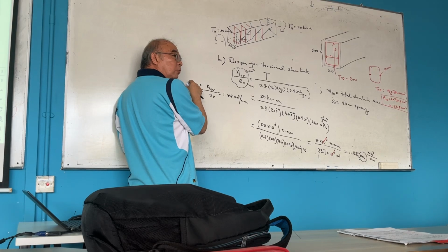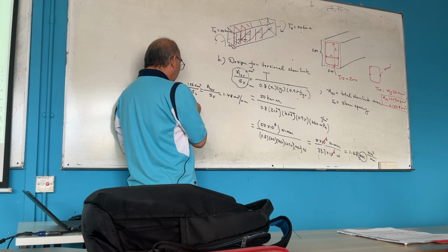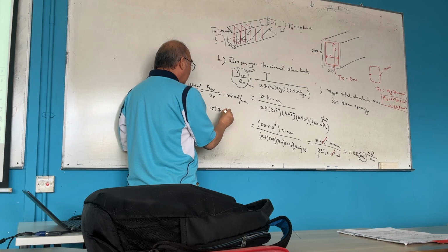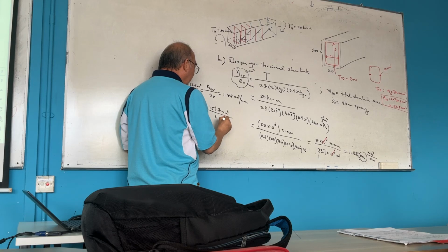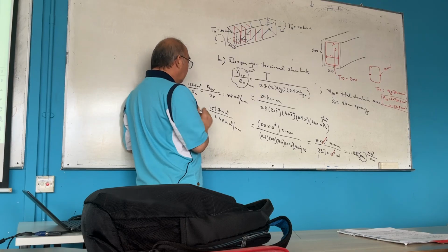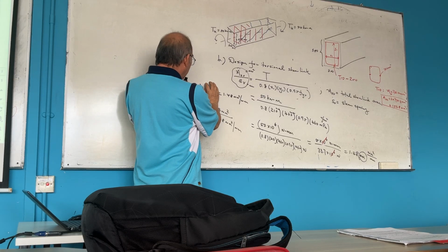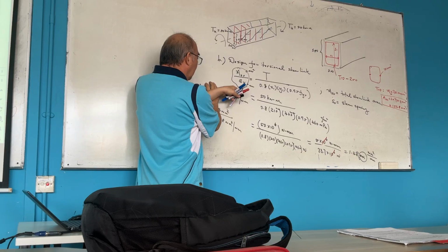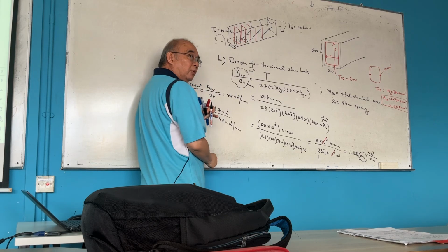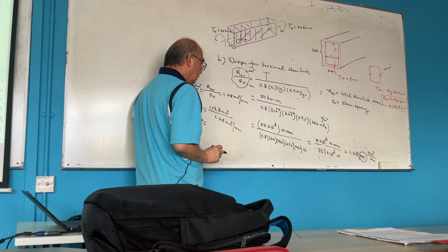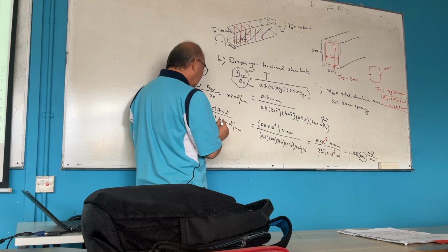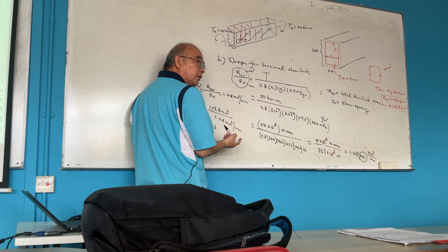Using ASV is 156.8. What is my SV? My SV would be equal to 156.8 millimeters squared divided by 1.48 millimeters squared per millimeter. If ASV divided by SV is equal to 1.48, you move this one over there, so SV is equal to 156.8 divided by 1.48. So what is this value here? 106. What's the units?